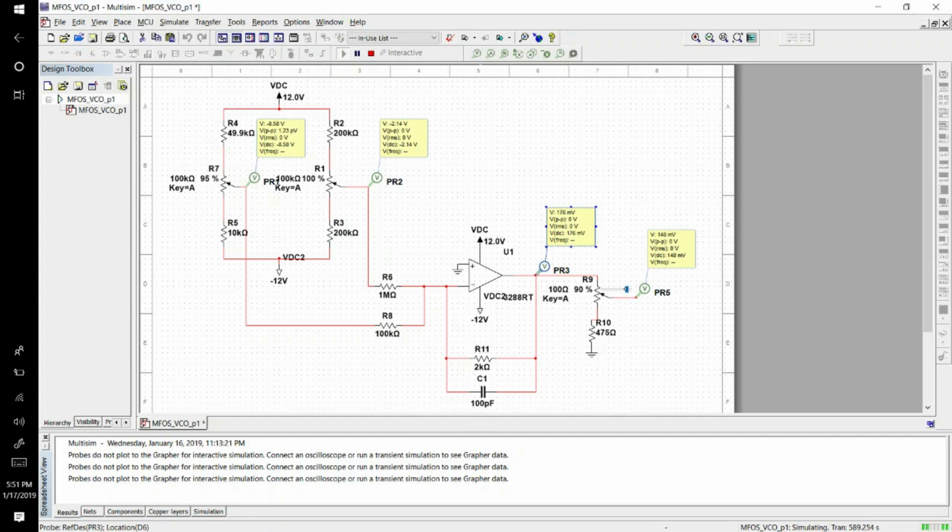So this is specifically here for tuning purposes. The requirement of having 18 millivolts per 1 volt of division is coming from our design requirement. It will be defining how many octaves our synthesizer can track. And after watching this tutorial, you're encouraged to find out why exactly it has to be 18 millivolt per 1 volt of division. But now let's go back to our slides.